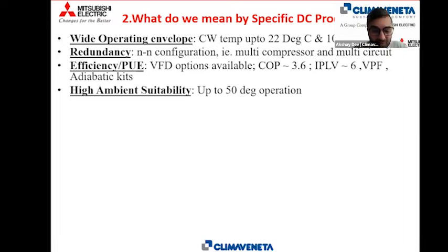We are seeing in specific areas, even in a place like Bangalore or even Mumbai, where ambients typically don't go above 38, 39, 40 at worst, hotspots being generated of 50 degrees, right? So you can't afford this. In a comfort application, you can have hotspots and your chiller efficiency will dip, but you cannot afford this in a data center.